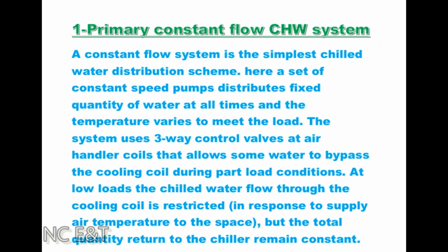At low loads, the chilled water flow through the cooling coil is restricted in response to the supply air temperature to the space, but the total quantity returned to the chiller remains constant.